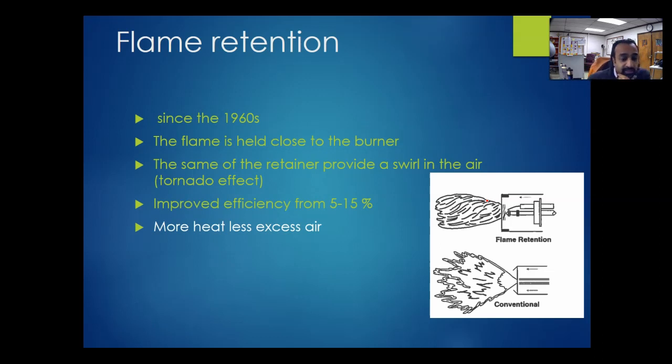More heat, less excess air. That sounds kind of cool, right? We don't want a lot of excess air, we want more heat. Increase the temperature from 300 to 500 Fahrenheit. That's inside the combustion chamber. That's a little bit significant, and I think it's worthwhile.